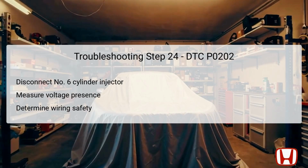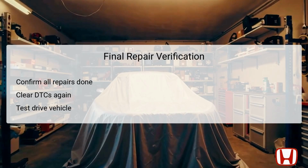This measure is crucial for identifying whether a short to power exists in the INJ-HS6 wire, ultimately affecting injector performance. If voltage is present, focused repairs to the affected wire are critical. In case of no voltage, testing can shift toward interpreting other underlying electrical issues, possibly originating from the injector control module, needing further exploration.